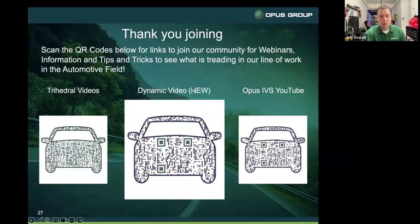Can Opus trigger key calibrations or perform variant coding? Newer stuff, yes, we can, but Frank, you need ultra fast internet, ultra fast. We're talking less than 50 milliseconds of latency, preferably probably 40. So we're talking fiber optic networking capabilities on your internet, and probably a hard line. No, we don't want to use the cellular capability, if you're using a DriveSafe, Wi-Fi, things like that. You guys need to have some really fast internet, but yes, we can do it.